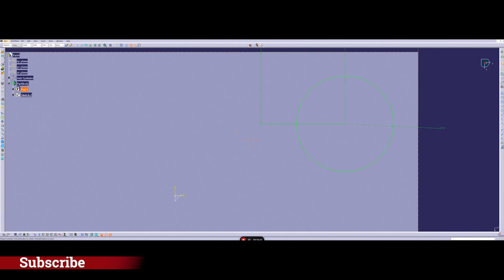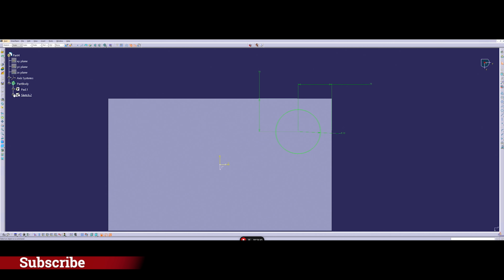If you cannot find the point, it's easy. You have to open the sketch, go to geometry and click the point. When you have the point selected, you have to go to this icon, which is construction standard element, and push this button, choose this command. You see that now we changed from the cross to a dot. So that means that now we have converted this point to a construction element, and the pocket command will not take it into account.